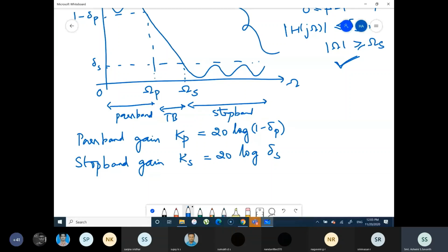Now we'll take the Butterworth filter, the first filter, and write down its frequency response. We are going to look into all the characteristics of the Butterworth filter, how many poles are obtained in the Butterworth filter design, and how you determine the poles. Once you write the poles, how do you write the transfer function? All this constitutes the design of the Butterworth filter. So everything from scratch needs to be done. First let's understand the characteristics of the analog Butterworth filter, and then we'll write down the design procedure.